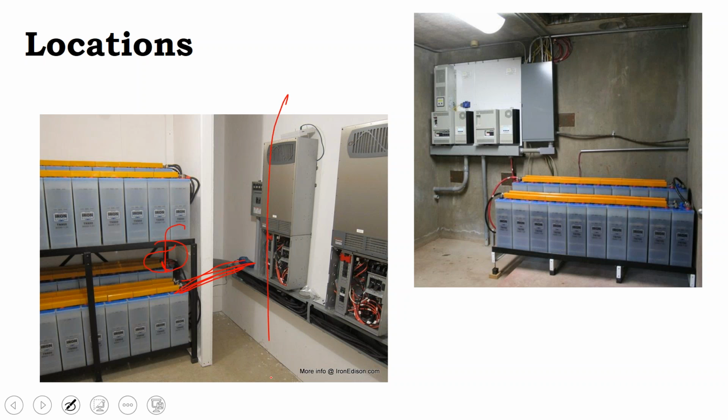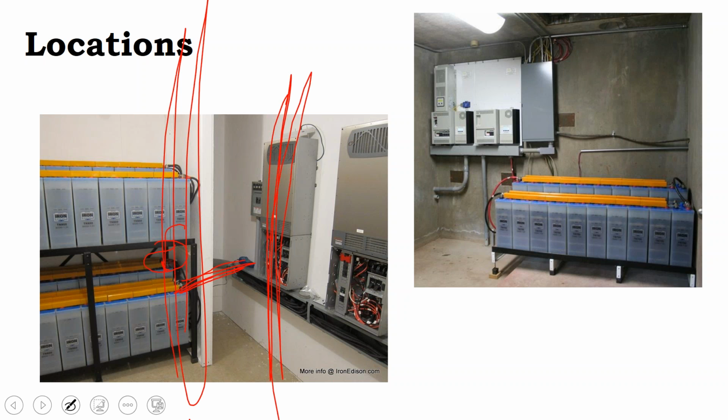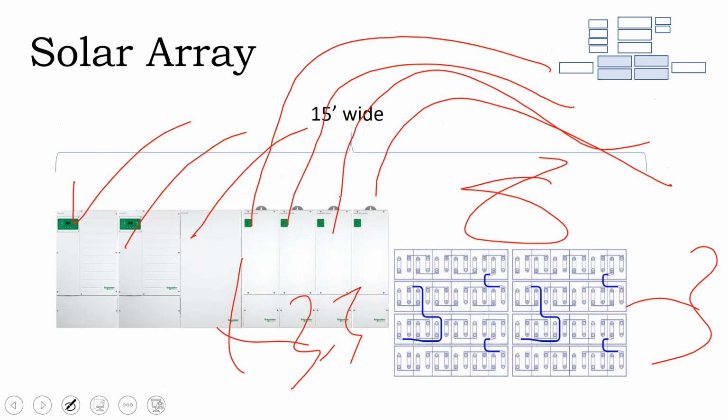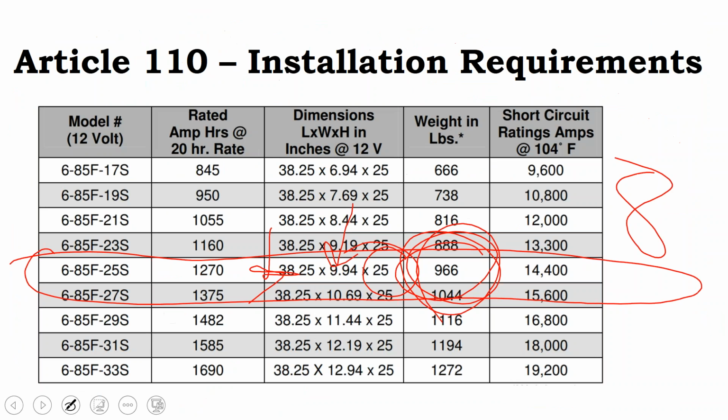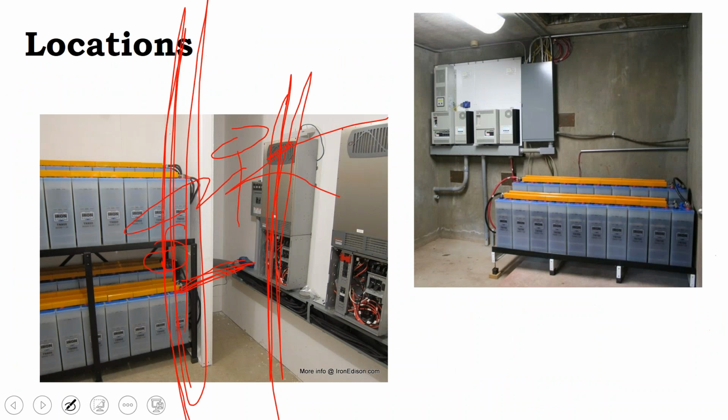And if you have another piece of equipment here and another piece of equipment here, and your back is to electrical equipment, that's where code might go a step further and say, well, generally that depth requirement is 3.5 feet, but there could be a condition where it's more than that. Guess where that condition is more than that. That's when you're kind of back to back against electrical rooms. So, what you can see here in this room, this is a violation.